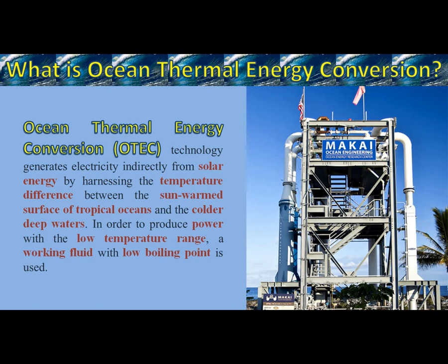What is ocean thermal energy conversion? Ocean thermal energy conversion generates electricity indirectly from solar energy by harnessing the temperature difference between the sun-warmed surface of tropical oceans and the colder deep waters. In order to produce power with a low temperature range, a working fluid with a low boiling point is used.